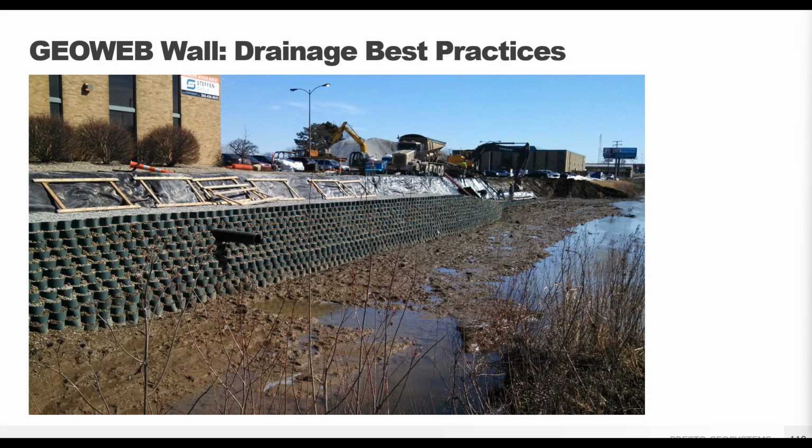Drainage is a very important topic that needs to be addressed with any MSE wall, including the GeoWeb wall system. Hydrostatic pressure buildup and improper drainage behind a wall face is the leading cause of wall failure, no matter the type of wall.